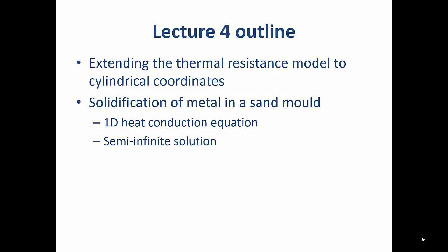Before I look at the answer to that problem, the outline for this session is to look at expanding the thermal resistance model to include cylindrical coordinates, and then moving on to look at a time-dependent problem related to the solidification of metal in a sand mould. And this is where, in terms of spatial dimensions, I deal with a one-dimensional heat conduction equation, but I also introduce time dependence, and then I look at a particular special case, the semi-infinite solution.